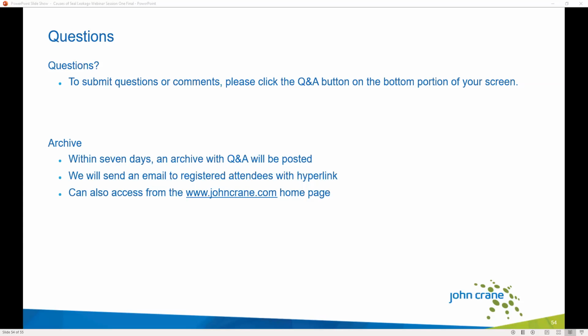And a lot of times what we see is a seal that was designed for a certain application or for certain pressures is exposed to different temperatures or different operating speeds or different pressures or changes in flow rate of the support system. And all of these changes can quickly affect how well that seal is performing. And most often that is what we see cause seal failures or cause seals to be pulled, is that the design and operation point for that seal has now shifted. It's being put into a different kind of operating mode, and it sees a change in performance and a change in the amount of leakage, and then the equipment gets pulled as a result.